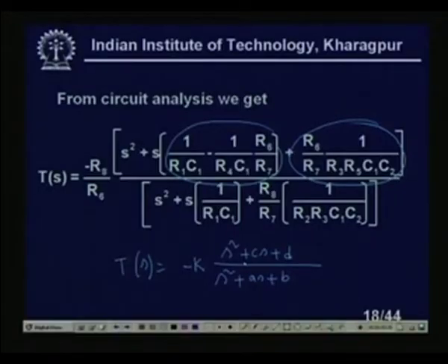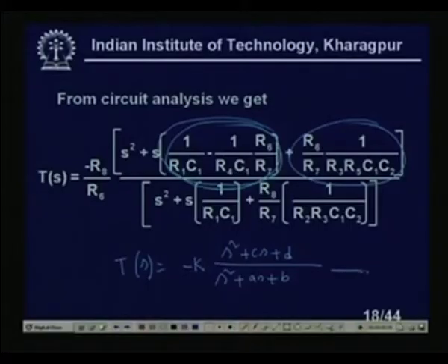So, in that type of situation, if this pole zero cancellation is not exact, if this coefficient is not exactly 0, then even though I try to realize the low pass structure, as you know, the pole zero pattern will be like this one, 2 complex conjugate poles and no zeros, we will find that it is not exactly the same pole zero pattern, right.